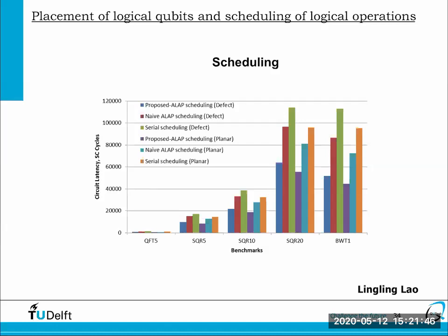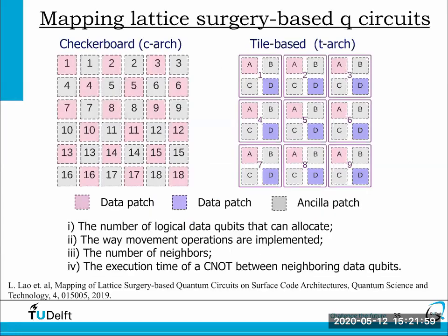The other thing is, when you go to logical qubits, what about the placement of the circuits? When you want to perform computation using logical qubits in your quantum chip, you have to define a kind of virtual infrastructure. You have to define places where you can place your logical qubits, because now a logical qubit is not a single qubit anymore, it's a set of physical qubits.